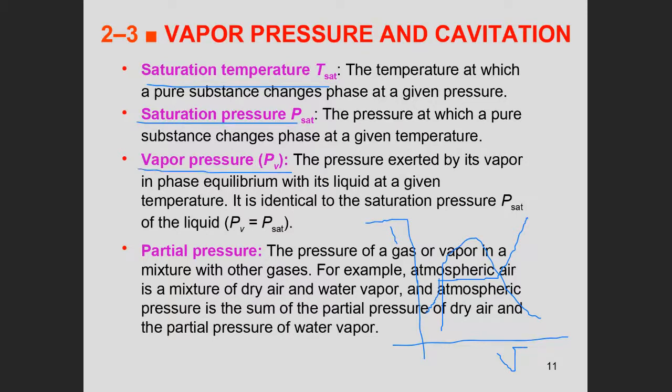The vapor pressure is basically equal to the saturation pressure, because at this point, do you remember, water starts to boil, if we're talking about water. At this point here, all the water has changed to gas. If you continue to add heat, we go into the superheat region. Right? So this is liquid, this is mixture, this is superheated gas or superheated steam.